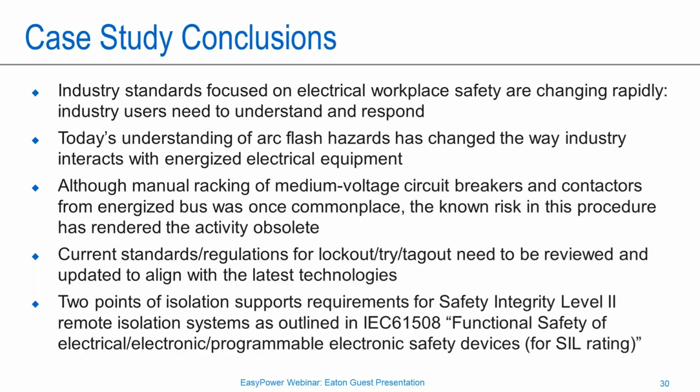I think it's important to understand arc flash hazards and how people interact with energized equipment, specifically with the 1584 changes. If you give some thought to what you might do in performing an arc flash calculation or study, the data collection is going to change. Now we're considering the orientation of electrodes and enclosure sizes. So again, knowledge around the standards is going to impact the way that studies are completed and how people interact with energized equipment.